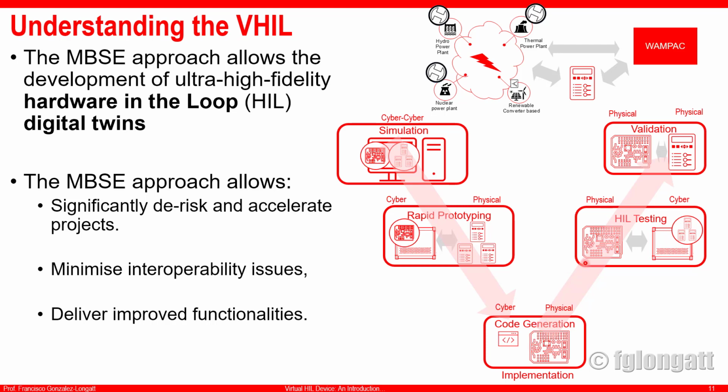But now, when the hardware and the software of the WAMPAC are ready, we need to test that the WAMPAC is properly working. And now what we will do is, here we have the WAMPAC as a physical prototype, and we use the real-time simulator to replicate the behavior of those relays, what we call the virtual relay, and of course the power system is inside the real-time simulator. Again, this is a physical cyber simulation.